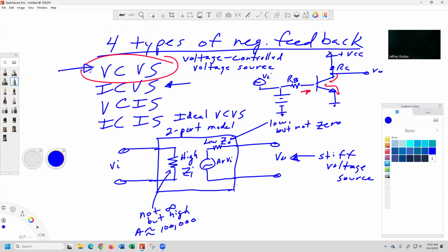It's the same thing. And again, I'll ask the question again. Why is it ideal to have this input resistance high? If this is a real small signal and this is low, it's going to draw current from my signal. I want my whole voltage signal to be here. Ideally, if that's open, the whole signal is there. None of it gets wasted or dissipated across this input.